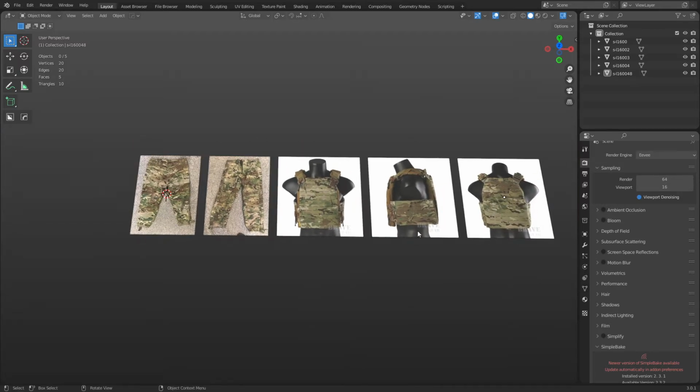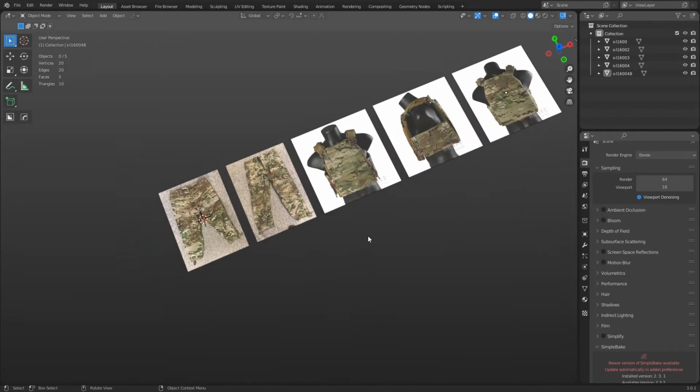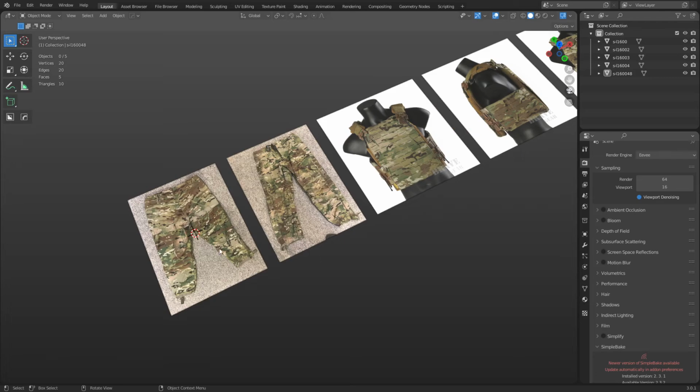You could use a newer version of Max or Maya, whatever, but all of this is going to have to go to 3D Studio Max 5 if you want to set it up on the bones for Ghost Recon. There's a file somewhere on ghostrecon.net. I'll have to find it again, make sure to point you in the right direction for that, but you'll be able to take whatever you model and put it onto the bones, and then do a little bit of weight painting for the vertex weights when you use the skin modifier, and then you'll be able to export that out from Max 5, all right?